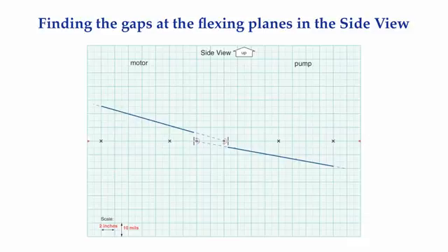Two different scale factors are used as shown in the bottom left corner of the grid. Going from left to right, one scale is used to show where the positions of the outboard and inboard bolting planes of each machine are located and where the shaft measurements were taken. For this example, the scale factor is 2 inches per major division.